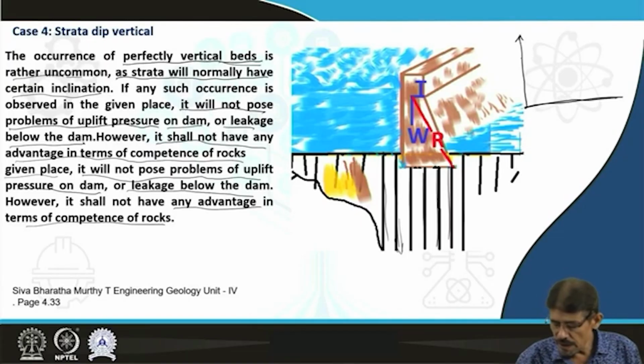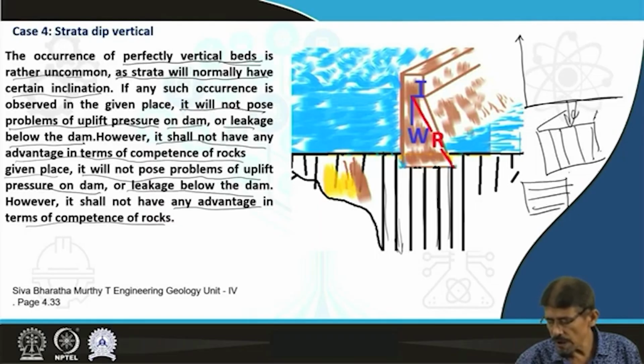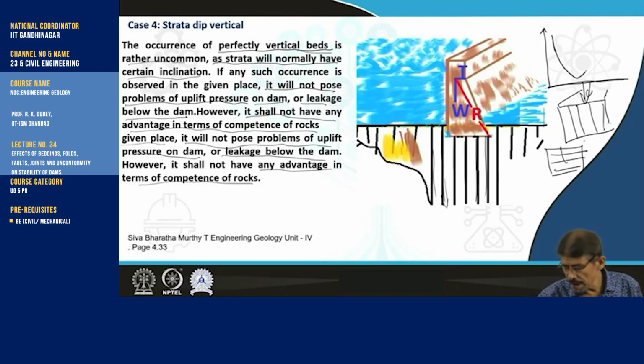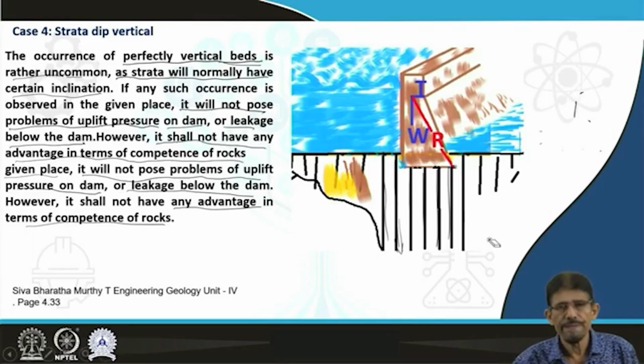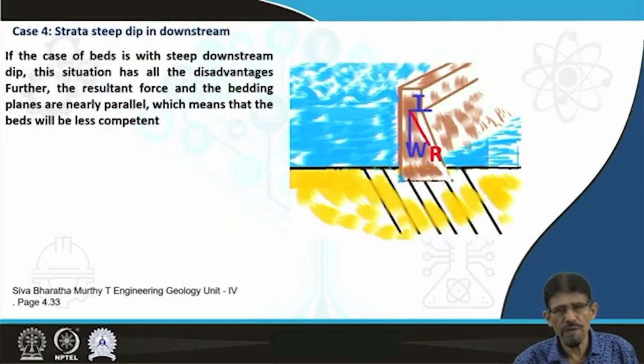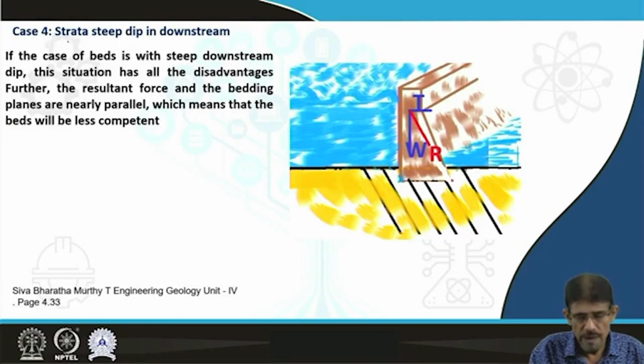Although we have discussed in general, if we test the rock block perpendicular and parallel to the axis, then the minimum strength is obtained at the position where the beddings or strata are inclined at 45 degrees, and there is a considerable value in the parallel and perpendicular cases. So in such situations the strata may be sufficient to bear the load in view of the strength of the bedding or rock mass. These are able to bear the thrust and others. Here the resultant is acting obliquely too, but the vertical extension of the beds is responsible for bearing the load of the resultant as well as the weight and thrust.